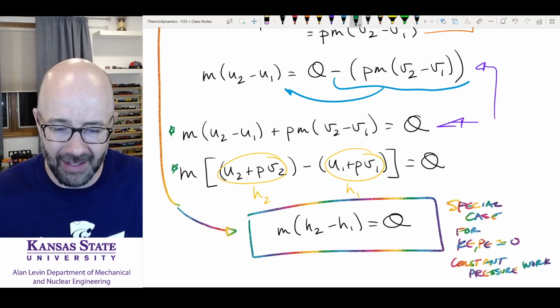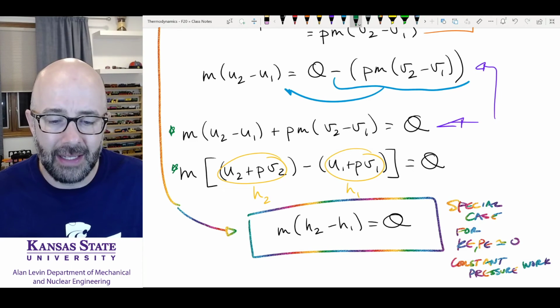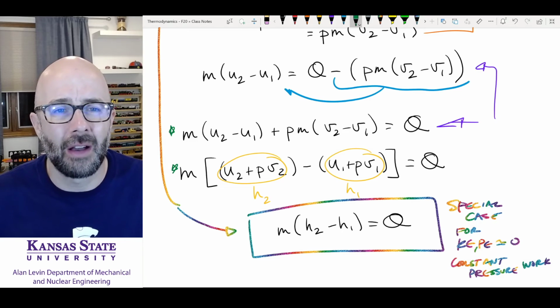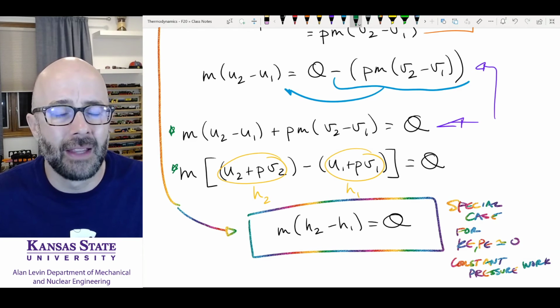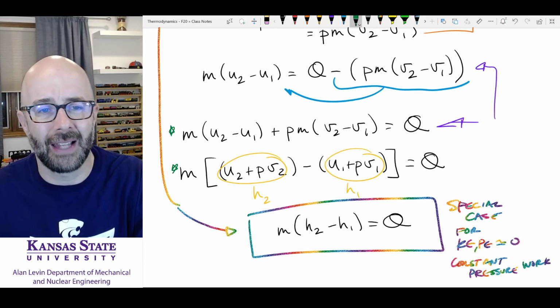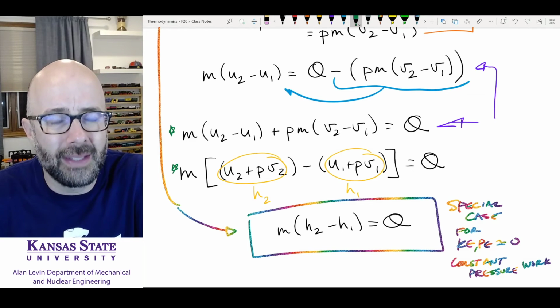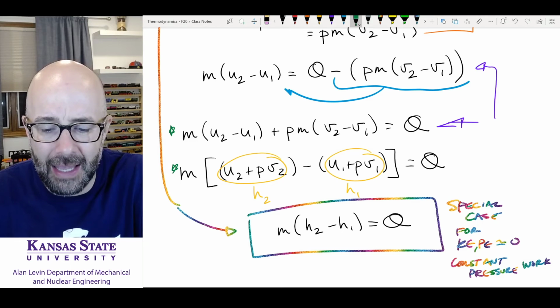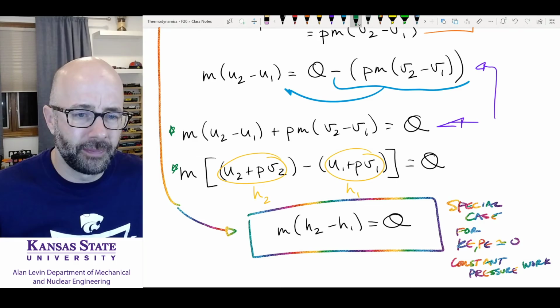It's the same X. You do need to understand that the values of internal energy and enthalpy are calculated, not experimentally determined. That's graduate student work we'll be talking about. But for these calculations, you're going to have a reference state with reference values, and we can see those when we look at our tables.